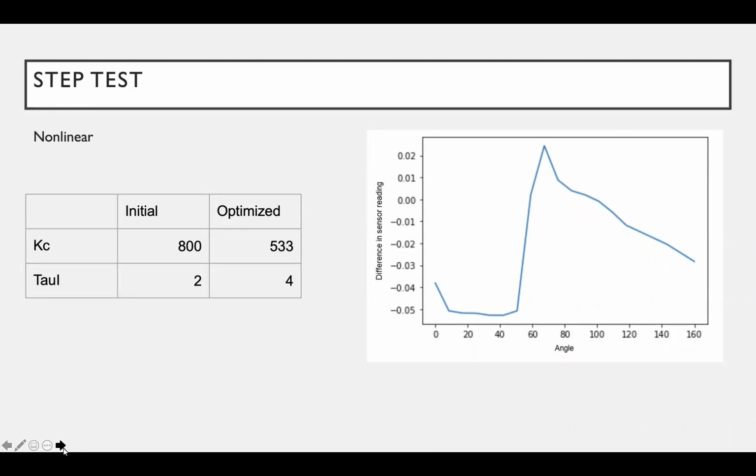And from this, we were able to develop a first order plus dead time model, which allowed us to have parameters to create a PI controller for the system. And even though the system is not linear, it gave us a good order of magnitude estimate so that we could manually iterate and change our Kc and tau I values until the controller was accurate, quick, and responsive.